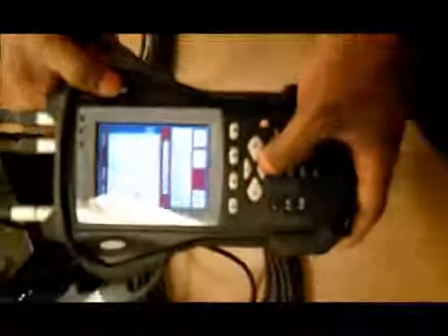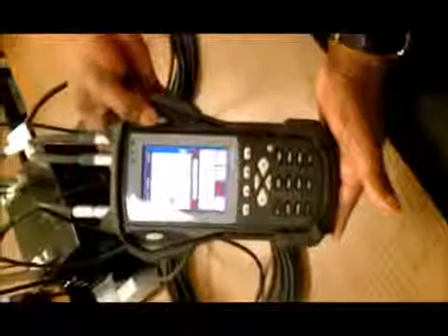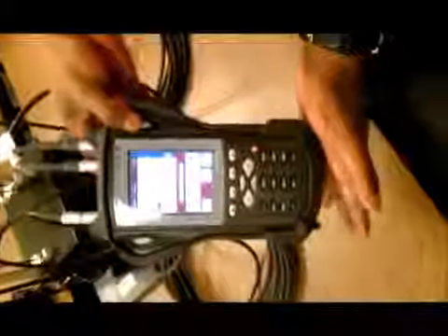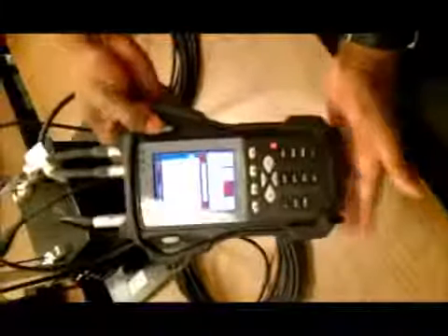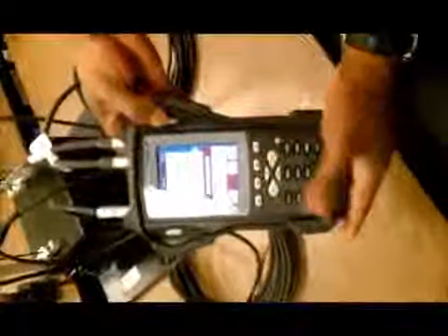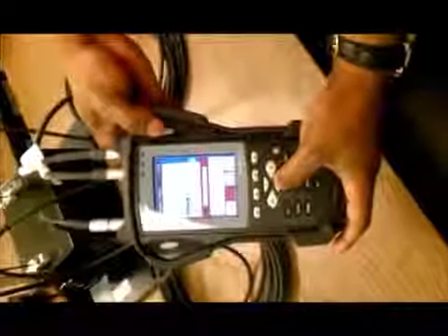Also, we have the ability to set up our X units either in Hertz or CPM. For this example, we'll use CPM. And then we have the detection type: root mean square, peak, peak to peak, true peak, and true peak to peak. So we'll go ahead and pick our peak to peak. And we have the ability to set a high pass filter to filter out noise that we don't care about. We'll leave that at 2 Hertz.